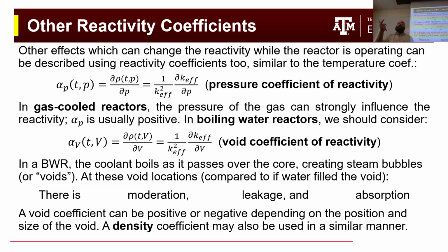The pressure is so high that even a significant change in the pressure of the system is not going to affect the reactivity that much, because the pressure is already at such a high point. I think the number, if I'm remembering it right, is that the reactivity feedback of a 2 bar pressure change is equivalent to the reactivity feedback of a fraction of a Kelvin temperature change. So the pressure can vary a whole lot before it starts to affect the reactivity of our system compared to things like temperature.